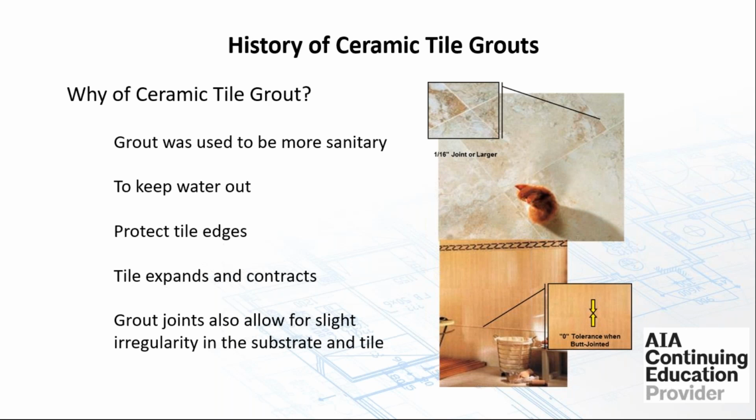I often wonder why so many times on a job site the least trained person will be given the grouting, where it can be such an important part of the finished look. It should be a trained finisher installing that grout, and not just the newest guy on the job getting stuck doing the grouting. Something to think about.